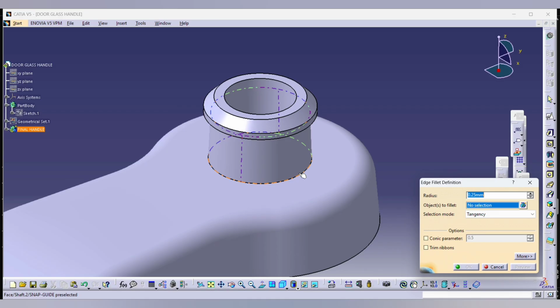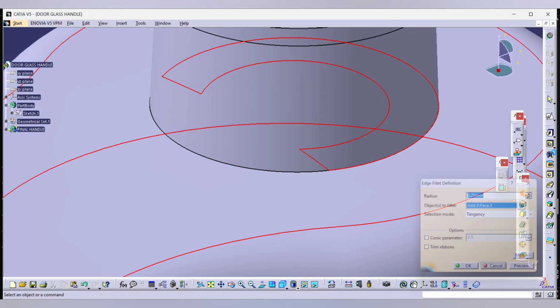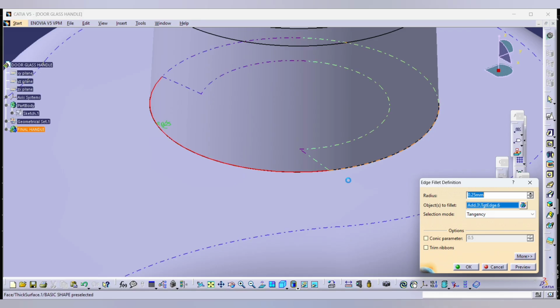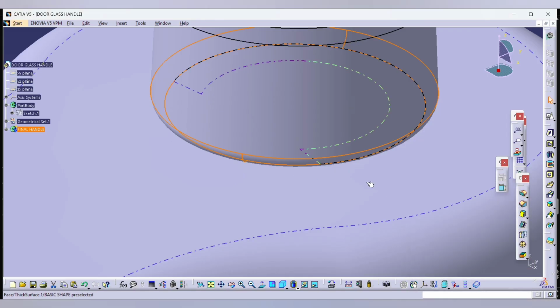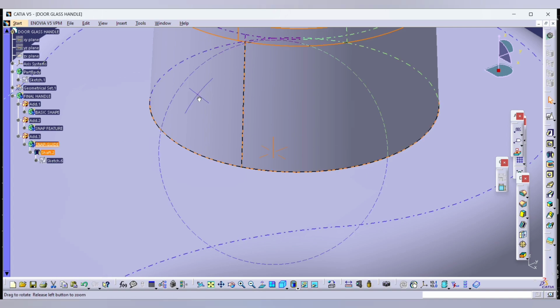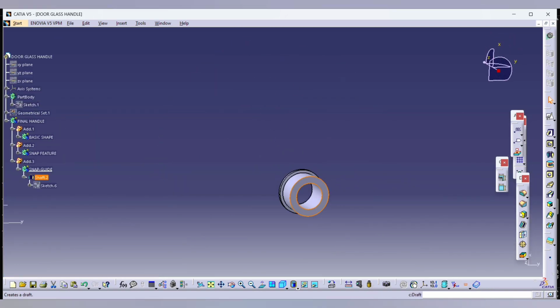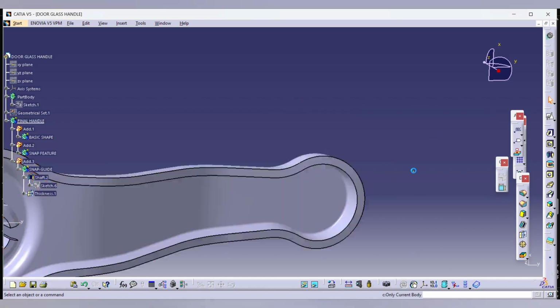Now apply the radius. So first of all, ensure all the bodies are merged. You can see here this body is not properly merged, so we'll apply some additional thickness at the bottom side, although it can be dampened in the boolean operation.